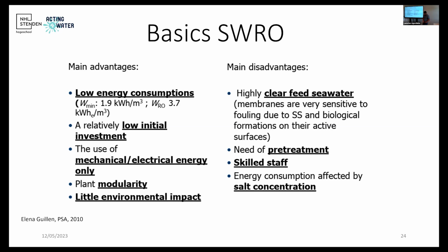you see also with your t-shirt, if I put water here, it will pass because the pores are quite big. But if I get a membrane with very small pores and I put water on it, it will simply not pass. So the smaller the pores are, the more pressure you need. So reverse osmosis or membrane systems require quite high pressure.